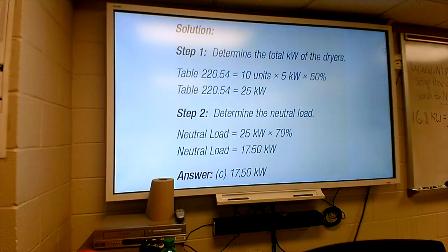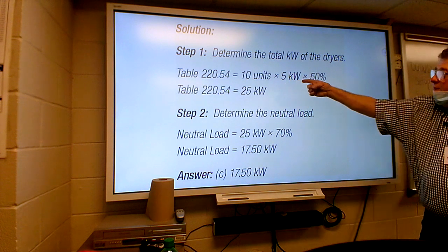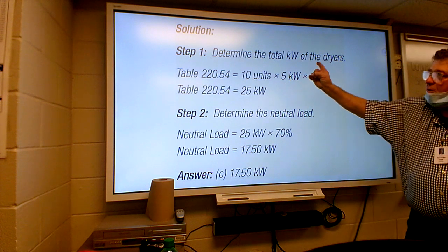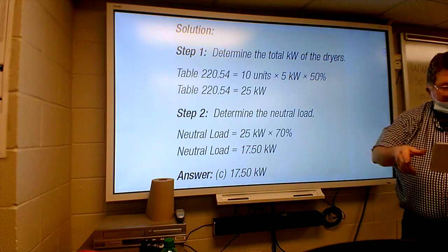So you look up and see what they're calculating. They stay in kilowatts this time. You see it on the neutral load. This proves that they did the other one wrong, and I knew the other one was wrong anyway as far as the units, but here they got it right on the very next one. They didn't say amps down here.